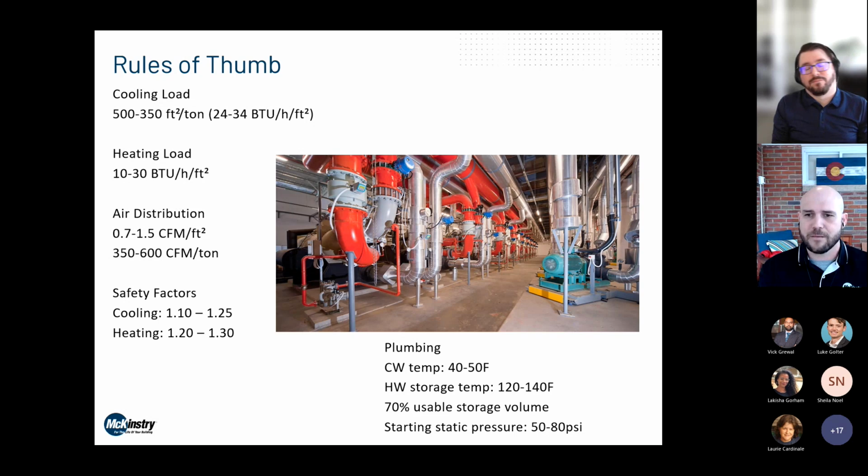Then all of a sudden you have a pump that's 21% larger than it ever had to be. Heating, again, is more conservative because freezing and bursting pipes is far worse than people sweating a tad. So those are a little higher.